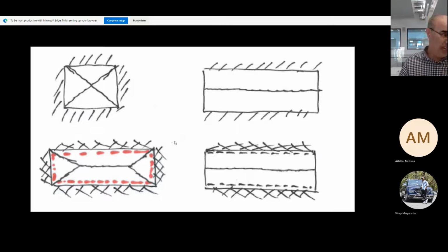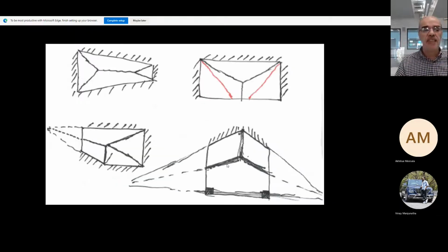It's the same story here. We have a slab which is rectangular, but fixed on 2 edges. So in addition to the positive yield lines where the curvature is maximum, you also have negative yield lines because the supports are fixed. Clear? Okay.